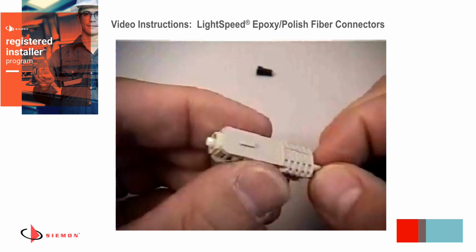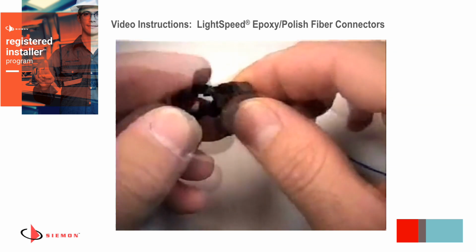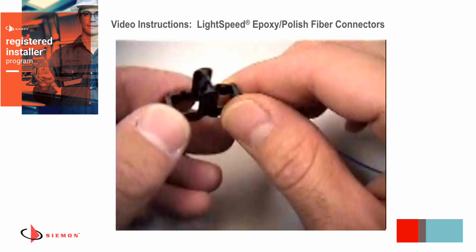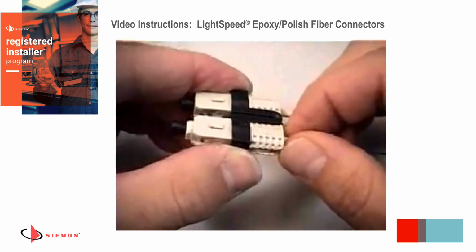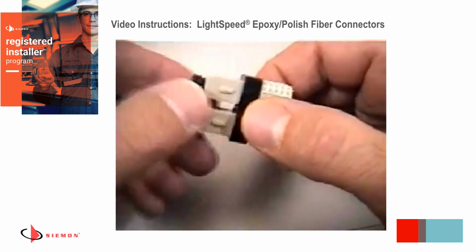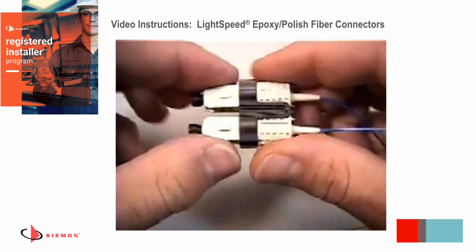Join two simplex SC housings to create a duplex connector by snapping together with a black duplex clip. Use the A and B designation markings on the duplexing clip to identify proper polarity. SC duplex connectors can be uncoupled by simply squeezing the front of the duplex assembly together or with a small screwdriver inserted as shown.